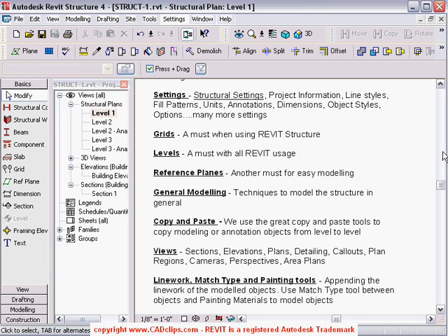So at a very quick snap of the fingers or click of the mouse, we can move a grid line or change a dimension between grid lines, and the whole entire Revit model will update, including the sections, the elevations, and the plans, and all that stuff. Normally, heaven forbid, someone moves a grid line. Well, that's a big job in traditional CAD drafting, where you've got to update a lot of stuff when one grid line moves, even if it's just a couple inches or a few millimeters. So in Revit, you move the grid line and that's it. Revit just pieces it all back together and stretches it all around.